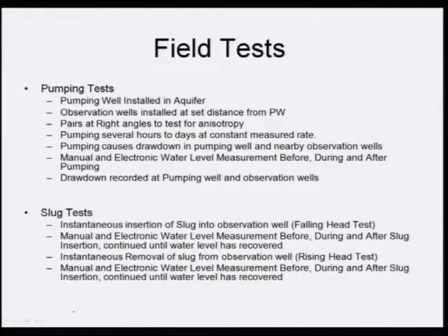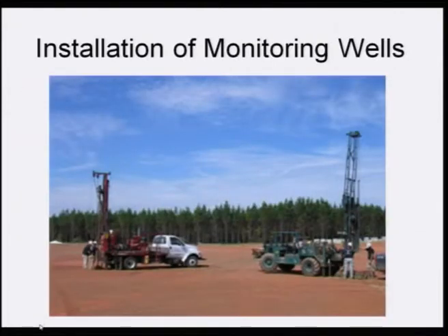So, last class we discussed two field tests, that is your pumping test and the slug test, which means an instantaneous insertion of a slug into observation wells, either as a falling head test, with manual and electronic water level measurement before, during and after slug insertion, continued until the water level has recovered. And now let us go back to how the monitoring wells are installed.